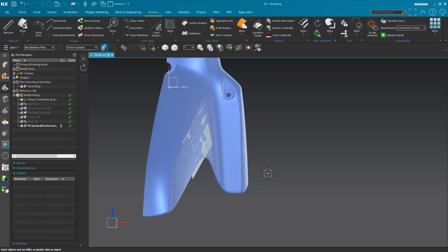The caps on a truck bed in cold weather versus hot weather, like in Michigan, you have an 8-foot-long truck bed, and you have those little caps sitting on top. On some of those, you'll have clearance for 25 millimeters of expansion and contraction, swinging between hottest weather and coldest weather. So it can be pretty extreme, depending on many, many factors. So expect to deviate from the scan.